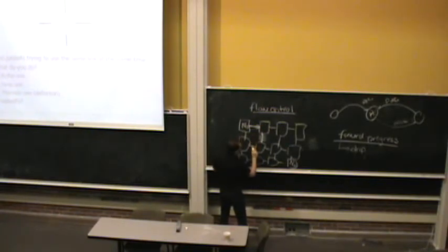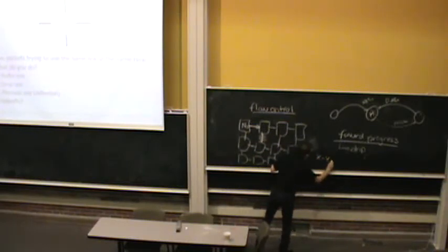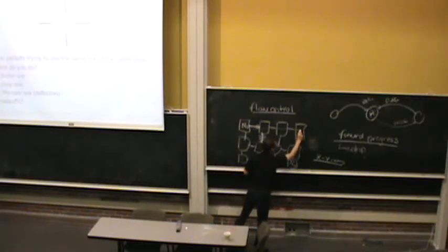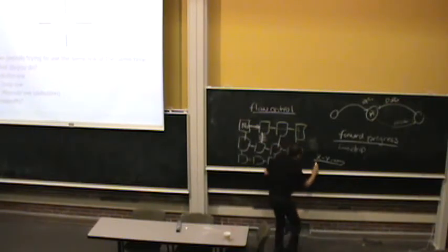Let's say the routing algorithm you employ is something called XY routing. The idea in this routing algorithm is very simple. If you want to go from one node to another, the message first traverses the X direction until it reaches the Y coordinate of the destination, and then it traverses the Y direction. Does that make sense? This is called XY routing, or dimension order routing, if you will.